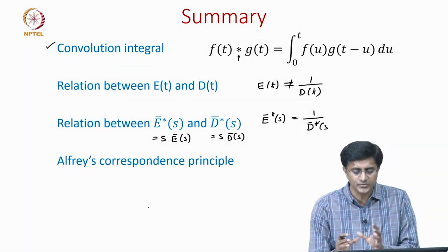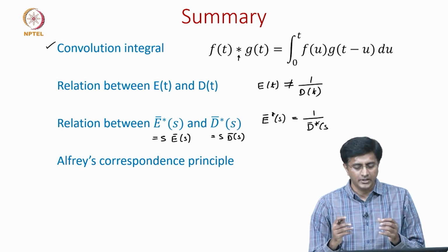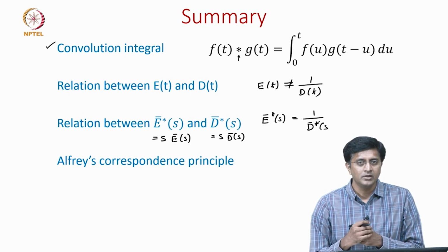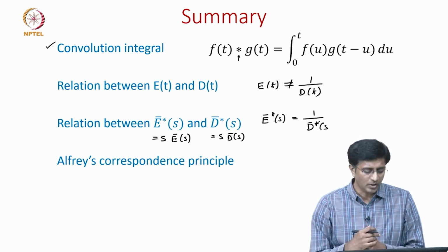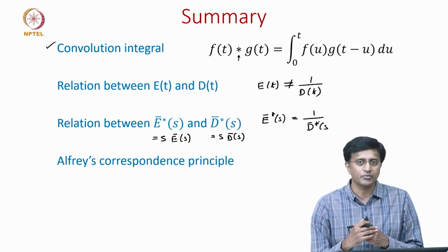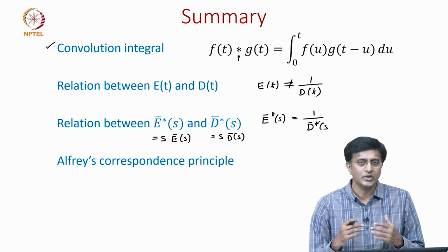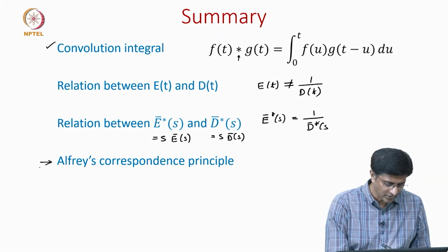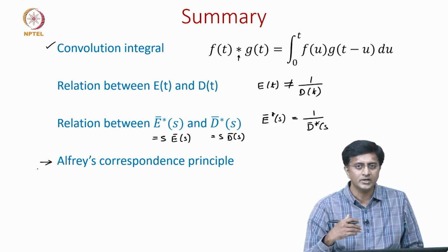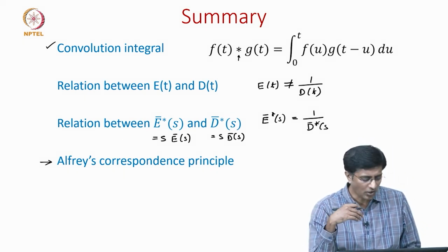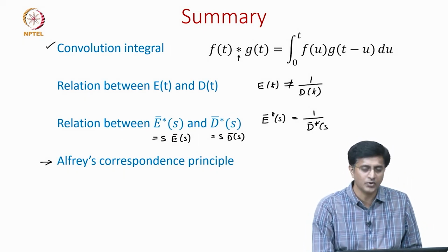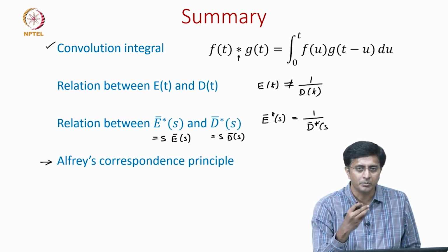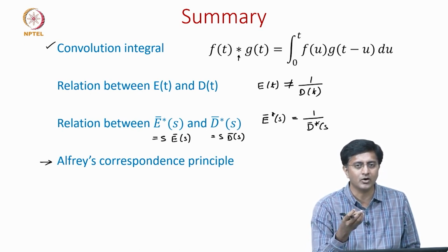And finally, once we observed that there is a Hooke's law kind of behavior in the transform domain, we took advantage of it to come up with a systematic procedure to solve viscoelastic problems, which we have shown using this Alfrey's correspondence principle. In the next 1 or 2 videos, we will see how to apply these correspondence principles to solve standard problems like analysis of a bar or analysis of a beam.